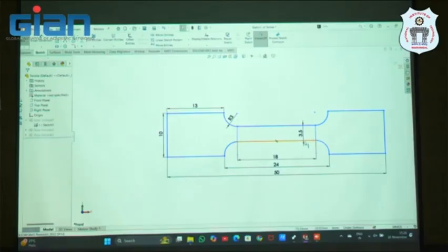Yeah, features are available, but the thing is, in Altair there is no direct feature like uniform lattice or gradient. We need to do that using some other option. Till now, whatever I have designed, those are uniform lattices. Uniform lattices means the thickness is uniform, pore size is uniform, every property is uniform. Gradient means from point to point it will change, right? The thickness and the properties, stiffness, everything will change actually. That's why we call it a gradient. That feature is available in Altair. That is called ramp. There we can do it like that.